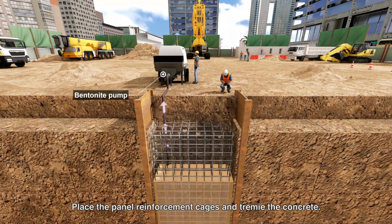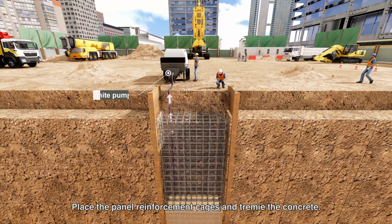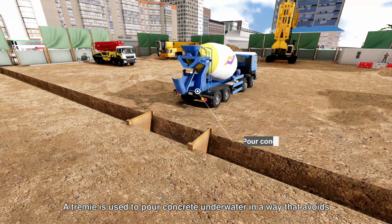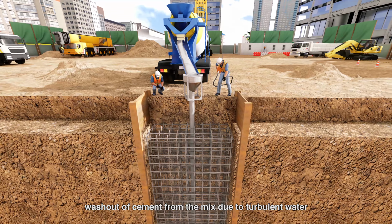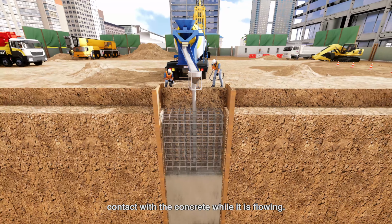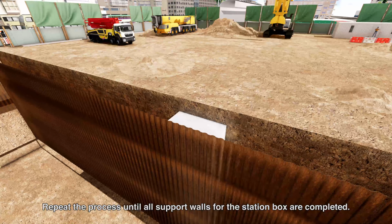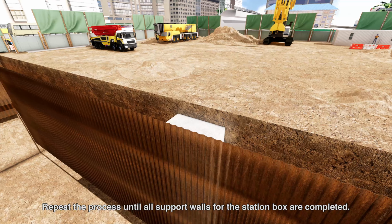Place the panel reinforcement cages and tremie the concrete. A tremie is used to pour concrete underwater in a way that avoids washout of cement from the mix due to turbulent water contact with the concrete while it is flowing. Repeat the process until all support walls for the station box are completed.